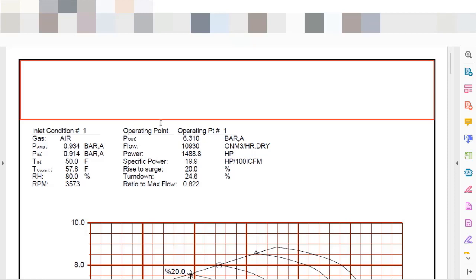On the other hand, the operating point, some information here is informed by the process engineer. For instance, the desired pressure at the outlet is information from the process engineer. The flow of fluids in this equipment is also information added by the process engineer, but the power calculated in this case is the responsibility of the vendor because it depends on the efficiency of the machine.